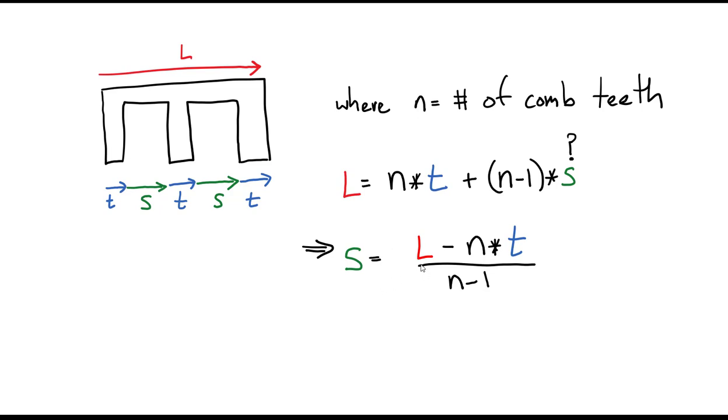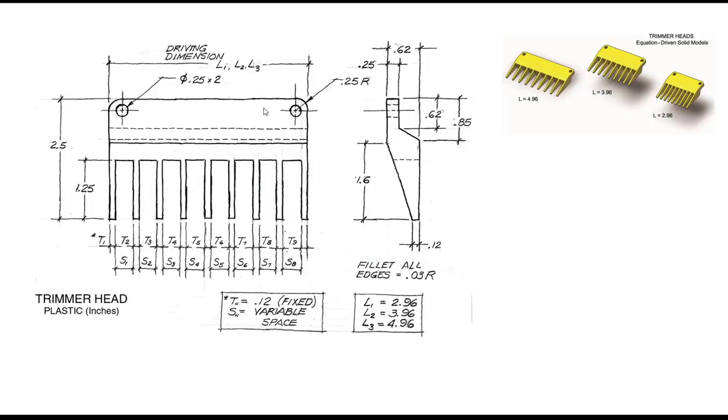So now I'm going to go through and explain how we could build this CAD model. Taking a look at the dimension drawings of the orthogonal projections, we have a front face and a right face. We want to first identify if there's any symmetry. In fact, there is a plane of symmetry right down the middle. Since it's 1, 2, 3, 4, 5, 6, 7, 8, 9, an odd number of teeth, that means this tooth right here, down the middle, is our plane of symmetry.